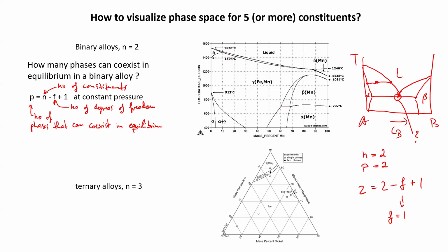Many of these phases we don't know, so it can be interesting if you work in multidimensional phase space. So one has to have a good way of displaying the phase diagrams and the phases and possible phase equilibria in your multi-dimensional, multi-component alloy.